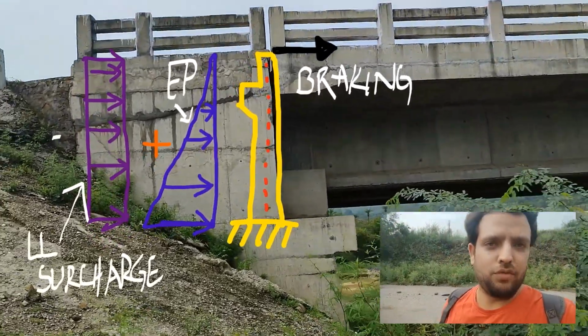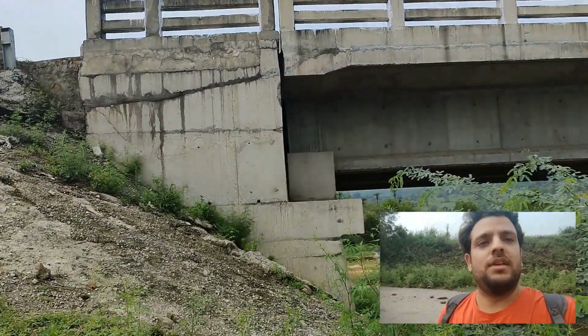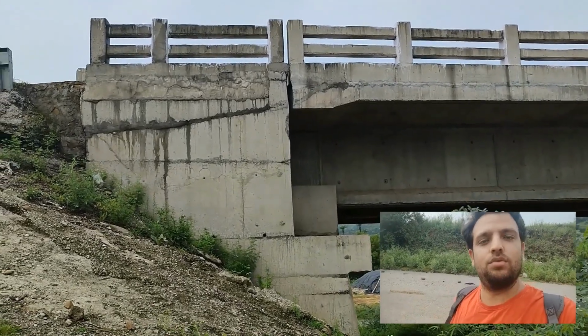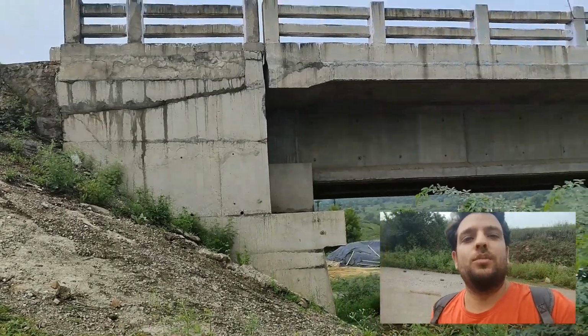Although they are subjected to a very minimum vertical force due to the moving live load traffic, that can be ignored because the horizontal lateral forces due to earth pressure, due to braking and due to the live load surcharge are more predominant than the vertical force. So this was component number 2.